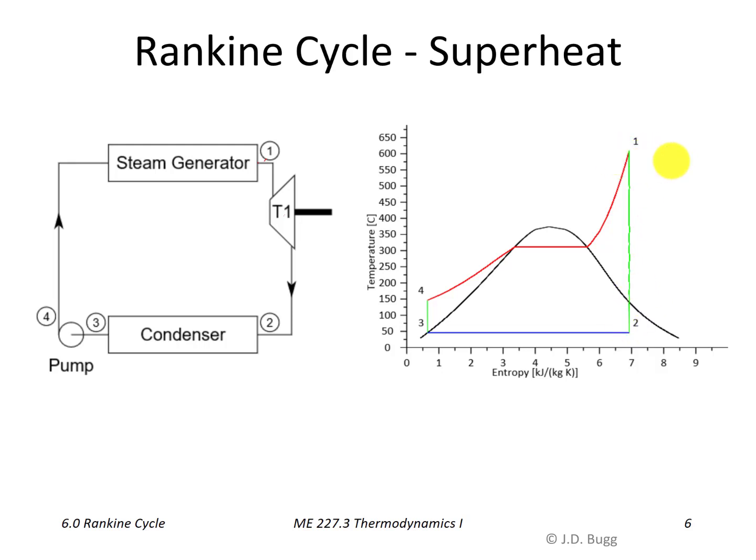So now we've got a Rankine cycle where the turbine process is much more realistic. Now we would still like to move this turbine further to the right. The next problem we want to address is related to the fact that this line is really quite steep. The reason that's important is, to move this turbine process over to the right far enough to get this bottom region of the turbine out into the superheated vapor region, the temperature at point 1 is going to get very high, and that's because this line is very steep. Remember, this is drawn to scale here using real data, so we can see this line is just getting steeper and steeper. So to try and move that over further to the right, temperature there is going to get extremely high.